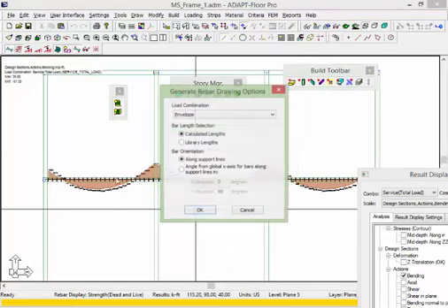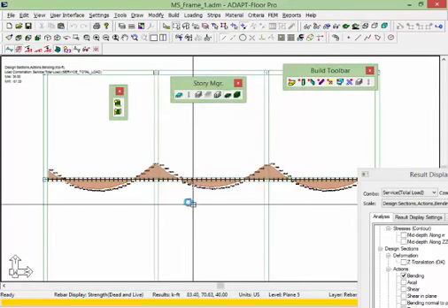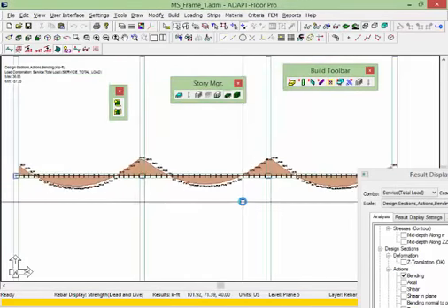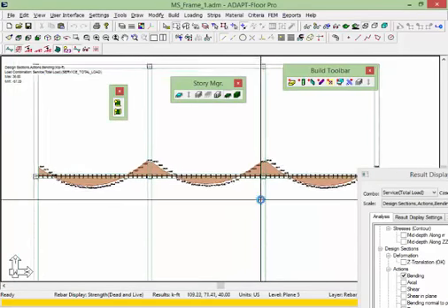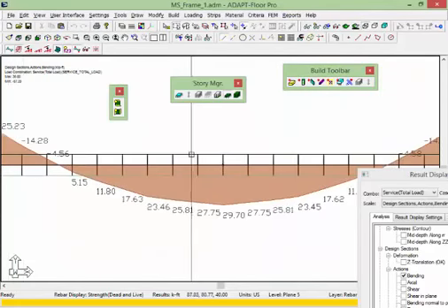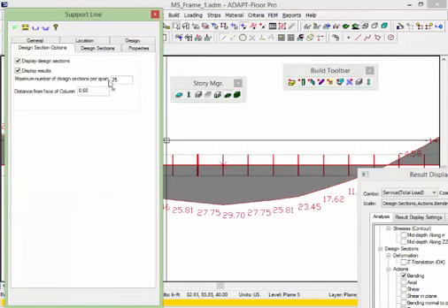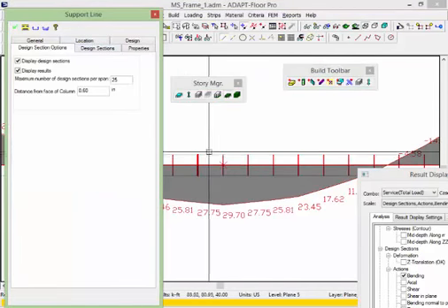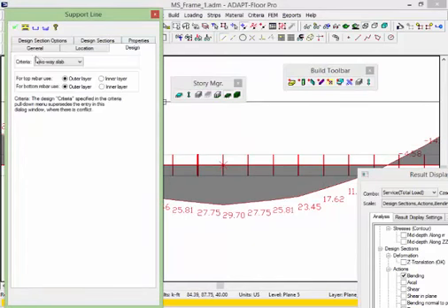Now, in this case, because we did not solve for strength, we're not getting any reinforcement for these beams. If you look at the beam itself, the properties of this design section under design is two-way slab. So clearly that's wrong. I need to set this to beam.